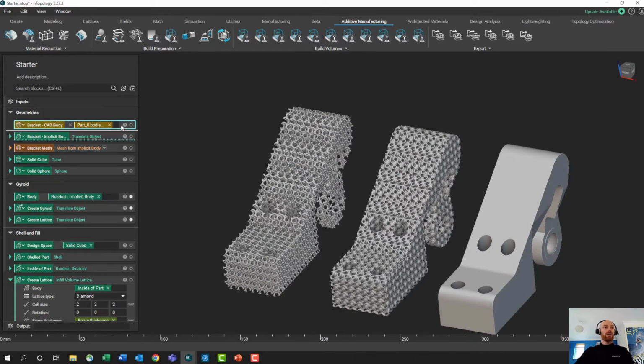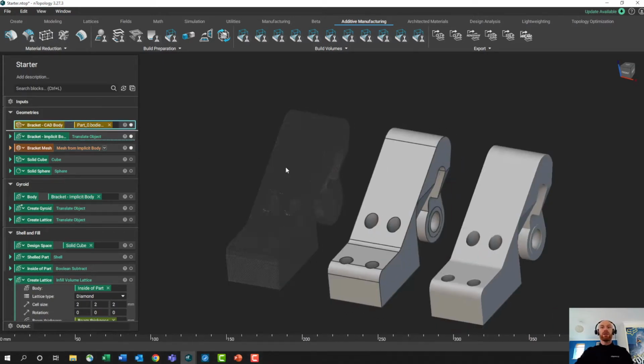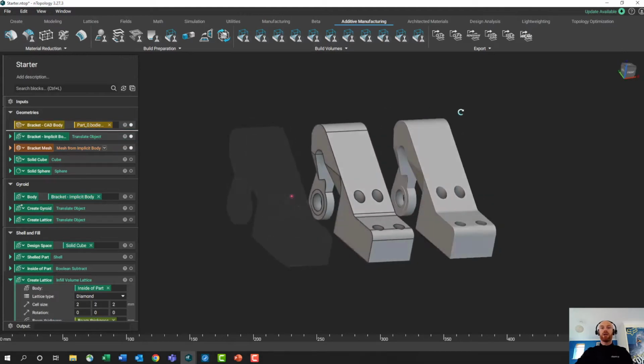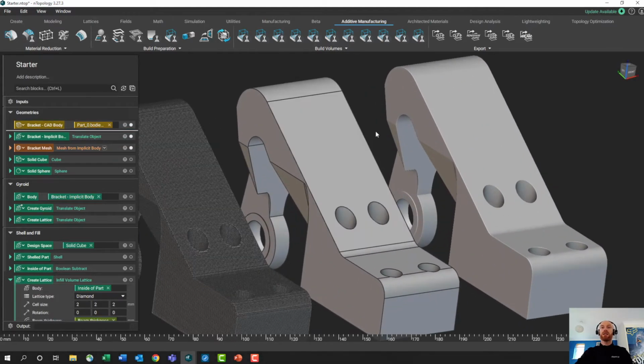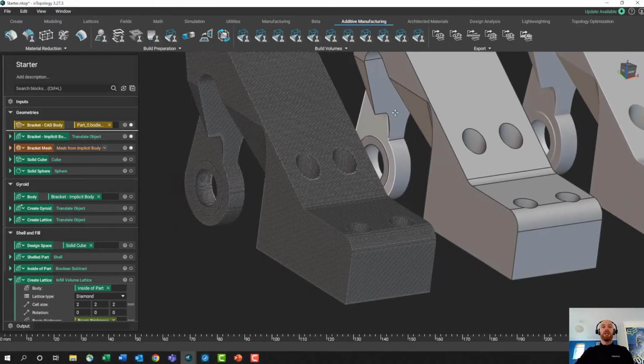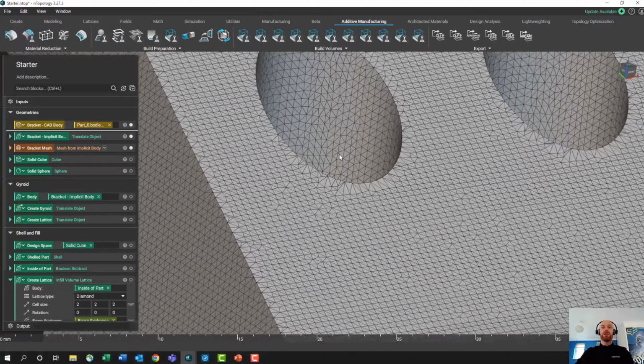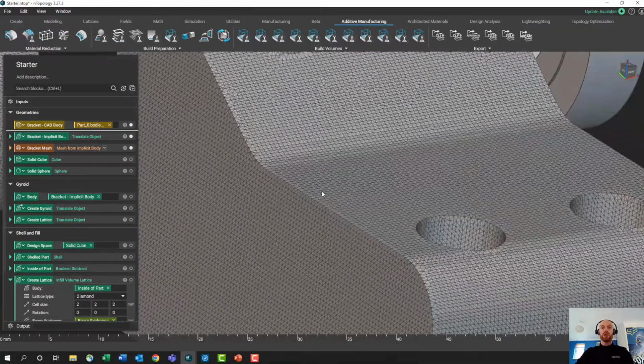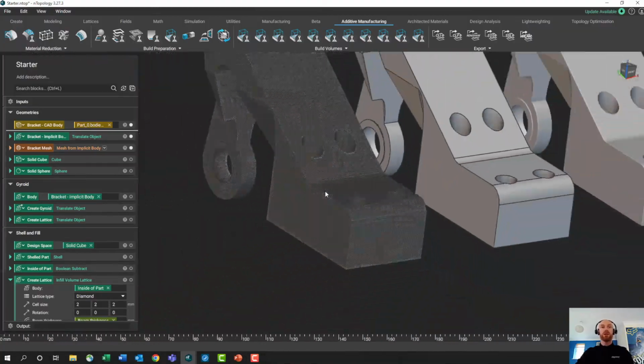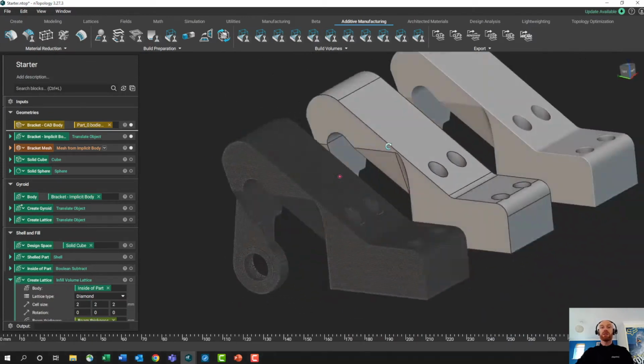Okay, so to go back to the view that we started with, these are 3 identical models. This is the same bracket. So the bracket was imported in as a step file. So this is in brep version. So you can click on faces, you can click on edges, and we can click on points, as we'd expect from a brep model. This has been converted into an STL file within nTopology. This is now converted into triangles, so it can be exported into another software or exported to build.